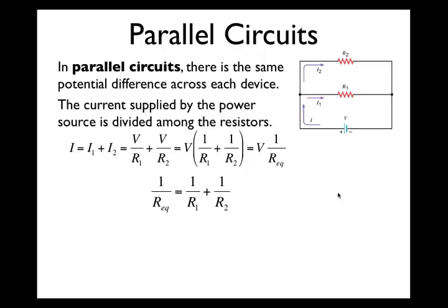The math may not seem intuitive, but I encourage you to think a bit about what the concept is saying. We're adding extra resistors, but the way that we're adding those resistors means the overall resistance of the network goes down. To me, the most helpful analogy in this is to think about checkout lines in a store or toll booths on a highway. If there is only one checkout line or toll booth open, all of the shoppers or all of the cars have to pass through that area.